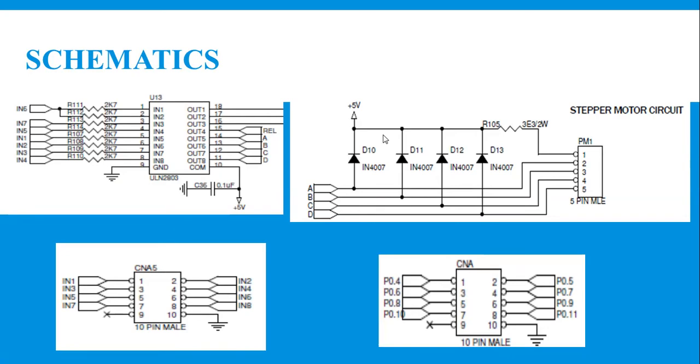Now coming to the schematics pertaining to the lab. Again, a stepper motor is a high load device. Your microcontroller alone cannot drive this. Thereby a motor driver is required. So we are now using a stepper motor driver, ULN2803. The function of this is explained in the earlier video. Here the permanent coils of the stepper motor are A, B, C and D, and these A, B, C, D in turn are connected to the A, B, C, D terminals of ULN2803.